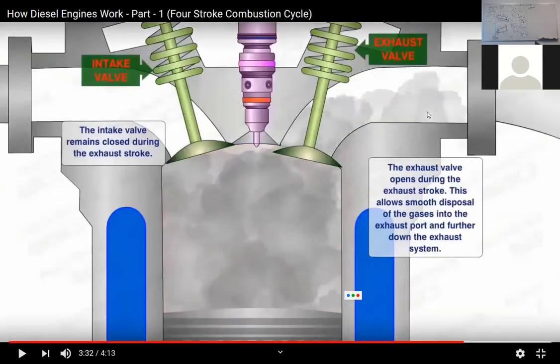However, we did not discuss much about the intake and exhaust stages in our analysis. Naturally, we have 4 strokes. We care about compression, heat addition, power, and heat rejection. But we neglect the intake and exhaust because these are open systems and would add complexity. So we talk about a closed system, assume it's air, everything is reversible, everything is pure, ideal. But naturally, that's not correct.